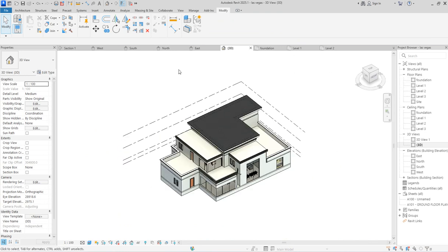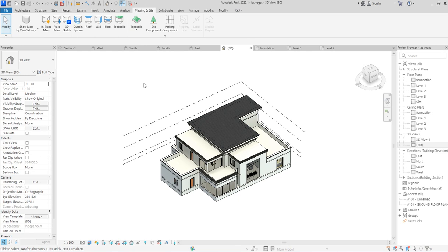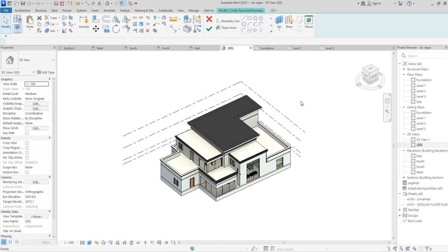So how do we start? Unlike before, when we used to do picking points, click on Massing. Here we have to create a surface, which we call Toposolid, unlike the Toposurface we used to create before by clicking points. This one is a little bit different. There are options like create from import and create from sketch. So you can decide that we want to create from sketch.